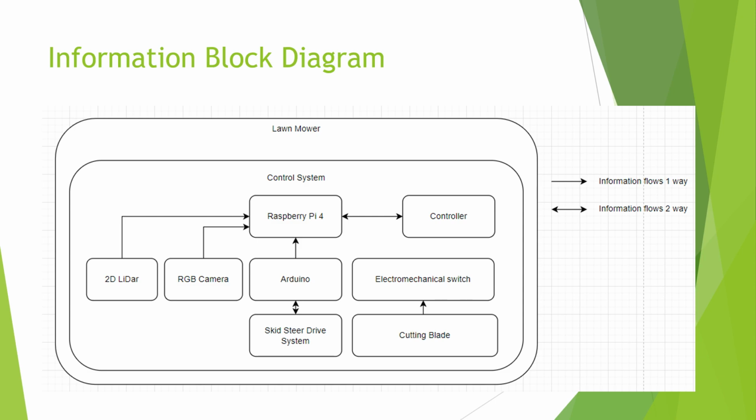Yeah, so like I said before, the 2D LiDAR is handling building the global map. The RGB camera is handling disturbances in the map, like if there's some obstacle to avoid. So it's just checking, in this case very simply, looks forwards. And if it's going to run over something, it doesn't. It stops and does its best to navigate around.